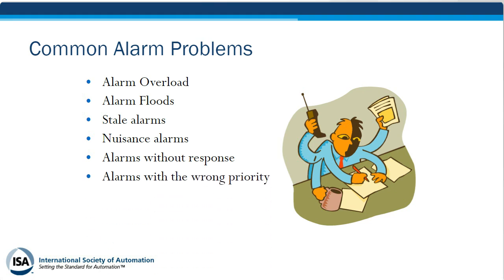we can go into that in more detail if we cover a more expansive view of this presentation, but I'm not going to get into that today. Redundant alarms, so it could be where we have a high and a high for the same tank, right? And then bypassed alarms. That's where people have alarms in bypass or jumpered out for extended periods of time. I've seen incidents in facilities where I've done alarm management projects where the alarms were bypassed for years. I mean, we're not talking days or months, we're talking literally years.